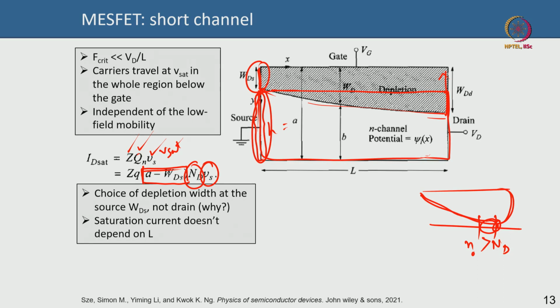Because if you want to maintain higher current but the velocity saturation is constant, and your doping density is ND, the local carrier concentration will locally increase compared to the background doping concentration. So the field will change its value, the doping concentration will change its value.